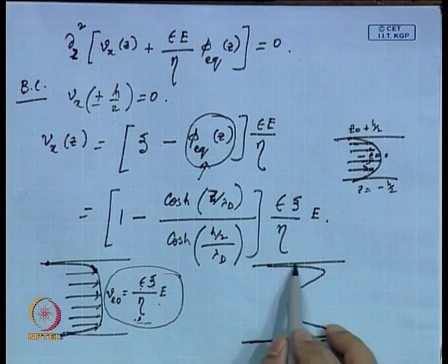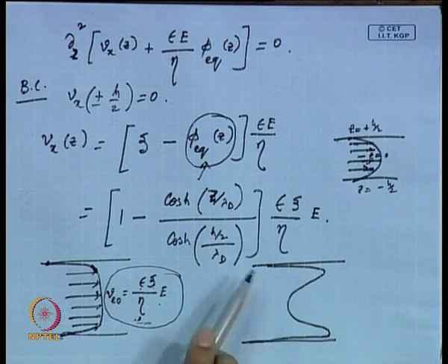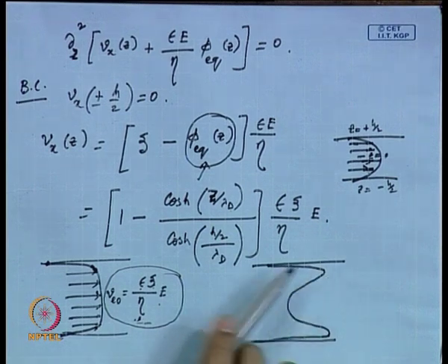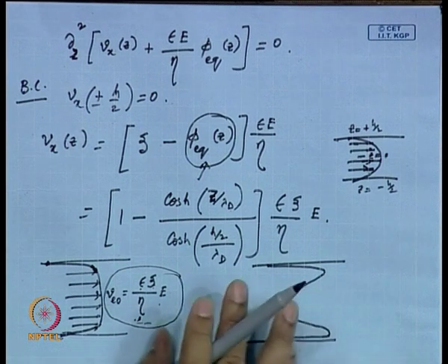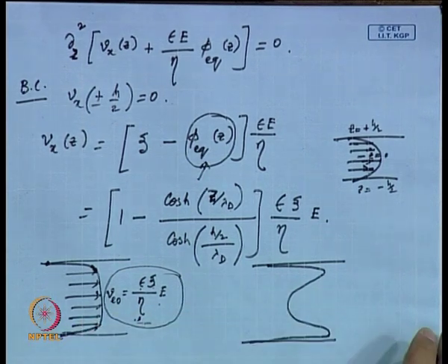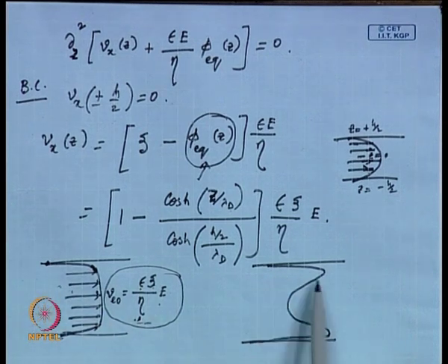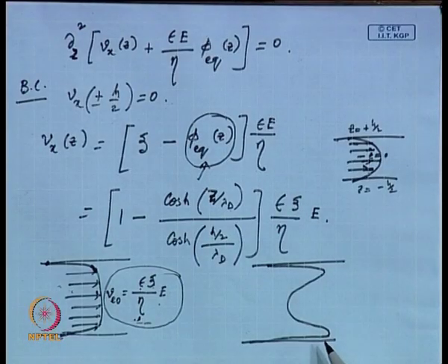Basically, this part you are following the electroosmotic flow, because here you have charges and this charge is trying to drag the fluid. Because of this ion drag, the bulk fluid is also dragged with the ion. So, it would be just like this velocity near the wall. However, you have a back pressure, and this is acting like a simple parabolic velocity profile in the opposite direction, because you have a p there and you don't have the p on this side. So, you have this kind of trend.